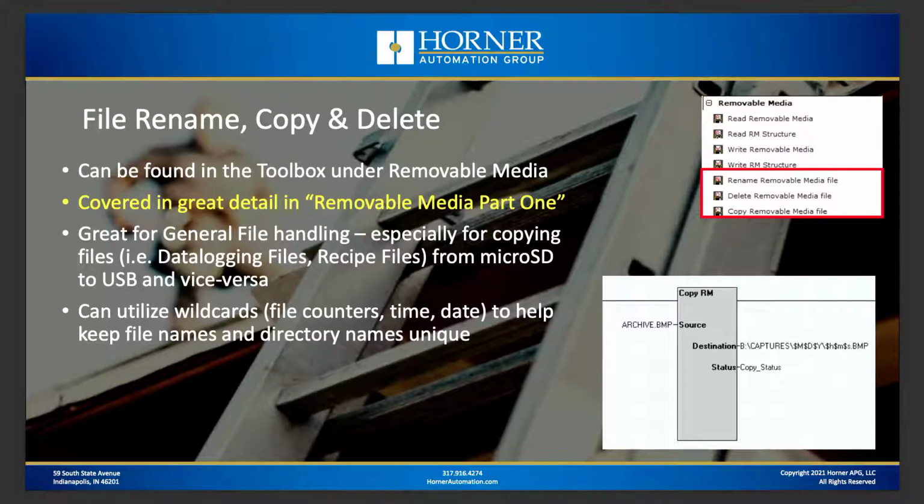But the rename, copy, and delete, those are just very handy, unique function blocks that can be used for general file handling, especially when you want to copy files, let's say data logging files or recipe files, for instance, from your micro SD drive over to a USB drive or vice versa. These functions also allow you, and again, we covered it in great detail in our previous live streams, to utilize wildcards, things like file counters and the current time and date, in order to ensure that your file names are unique and your directory names are unique, so you don't end up overwriting a file you don't want to overwrite. So that's the file rename, copy, and delete.